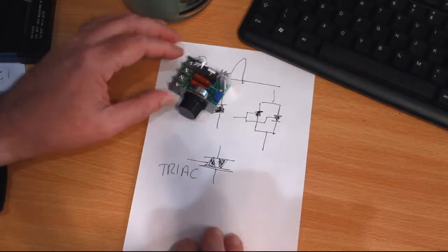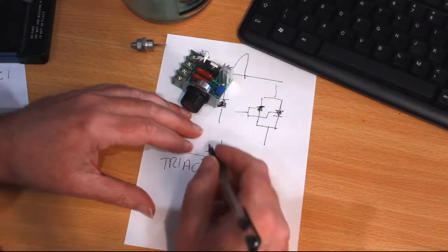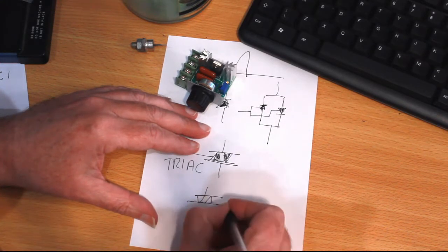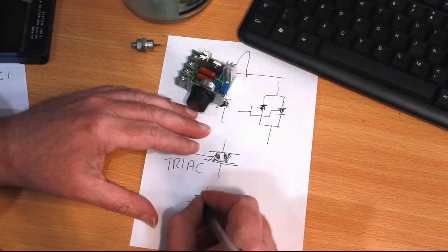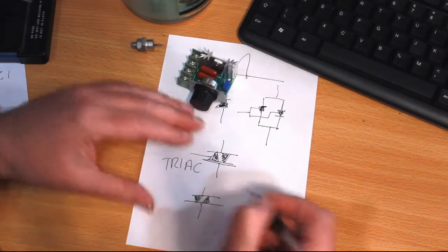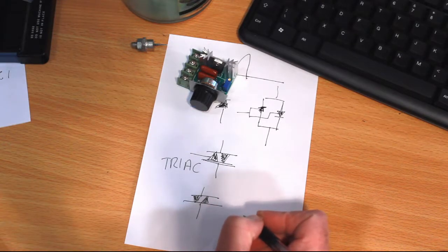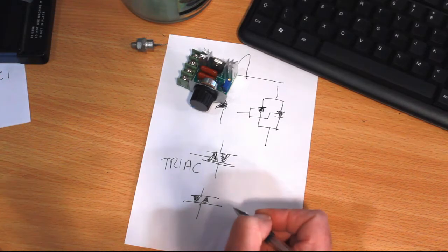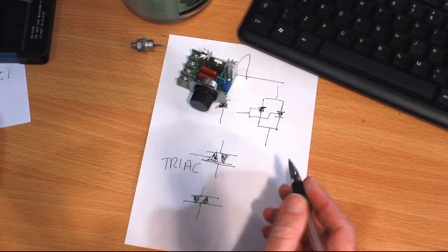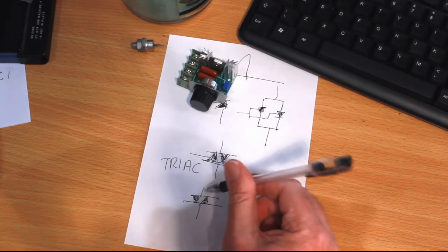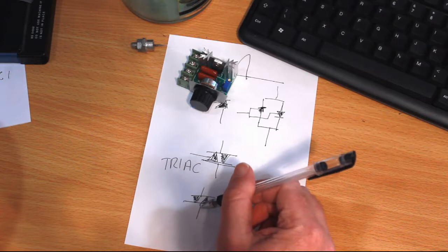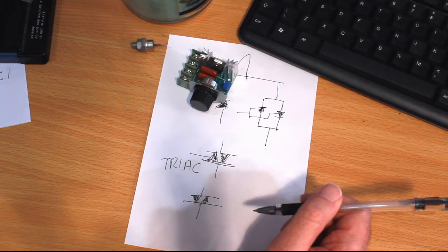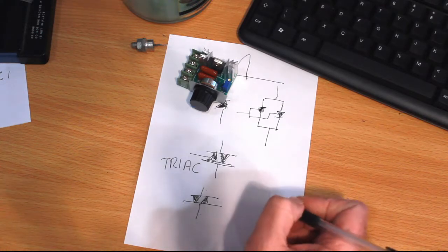We get a bit of paper back. I'll get a bit of paper back. A diac is a triac without the gate. Thing with the diac is it doesn't turn on. They don't turn on until they get a certain potential across them. Once they get a certain number of volts across them, they'll let go and they'll conduct. And by controlling the rise of the potential across the diac, you can control whereabouts in the phase it triggers. It's a phase shift type device.